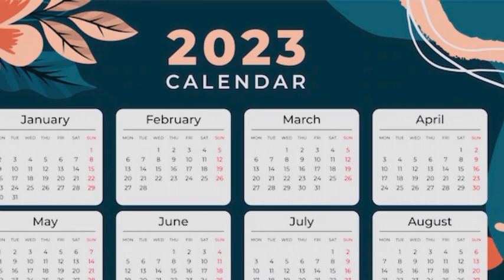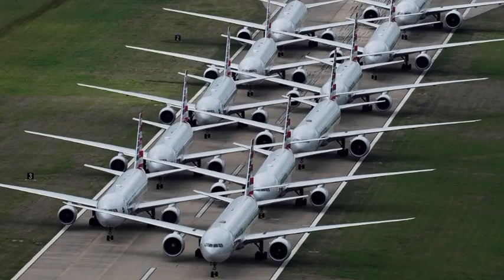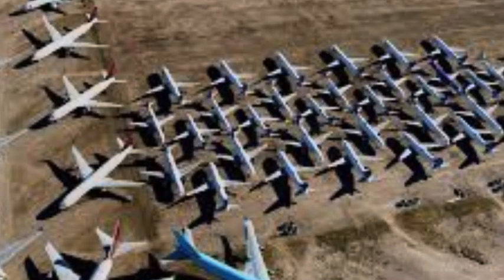And besides, there is, for example, a calendar month period on the landing gear as well. Mostly 8 years or roughly 10 years is assigned for the landing gear. Let's say, for example, a landing gear is attached to an aircraft, and then after some flights, the aircraft is parked for a prolonged time without being in flight and in service. So when 8 years or roughly 10 years has passed on the aircraft, the landing gear is no more serviceable and it should be removed and sent for the overhaul.